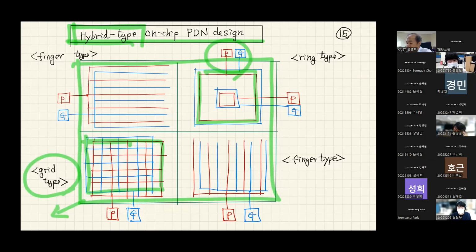This could be the digital processing area, where a GPU might be placed. Sometimes an RF circuit could be placed here. An RF chip doesn't use as much switching current, so we can have some relaxed PDN requirements. Sometimes these metal layers can be used for RF circuit applications such as high Q filter design or high Q inductor designs.